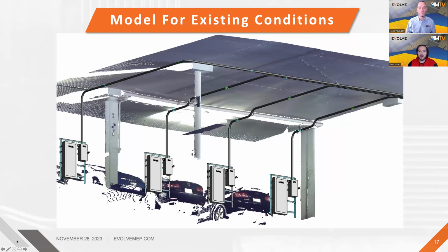Absolutely. And a lot of that depends on what you're scanning, and what you want to use it for. If I'm a crime scene investigator and I'm using a scanner to capture a crime scene, I want every point I can get, given how much time I have. However, if I'm using it in the construction environment where I'm really just trying to coordinate around things that are there, then the point density is not as important. But then again, if I'm in manufacturing and I'm using a scanner to scan an existing object that I'm going to then mill out, again, I want every point I can get. So a lot of it, with the point density and the scan time, is dependent on what the use case is. But I agree, it's always true that more scans is always better.